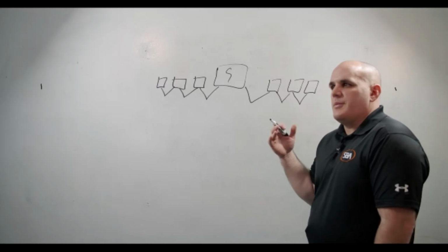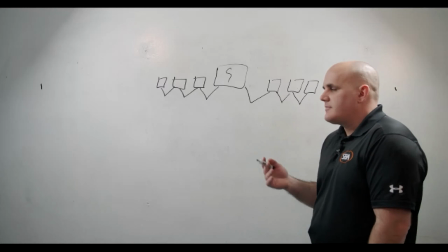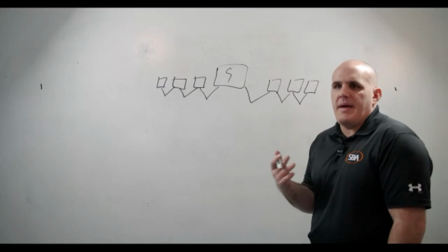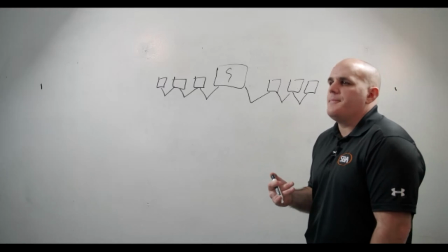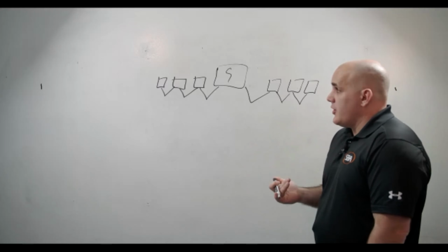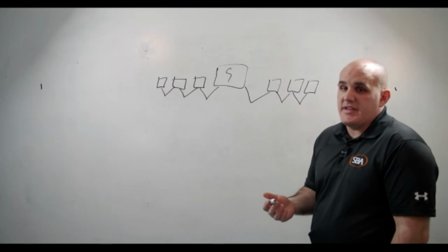If someone changed a controller and it's offline, it's most likely a MAC address, device instance, or baud rate issue, something like that. If you have a lightning storm and all your controllers go down, it's most likely a transformer issue.